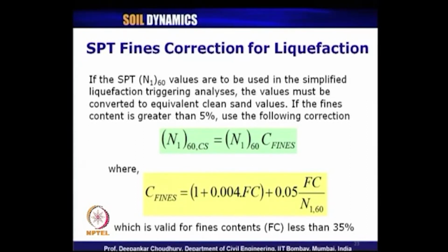No correction for fines is required. But if the percent fines exceeds 5%, then this is the correction we should apply on the corrected value of N160, which we got after making all the previous static corrections.